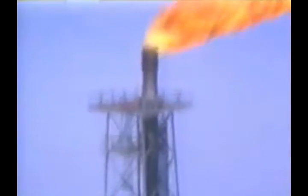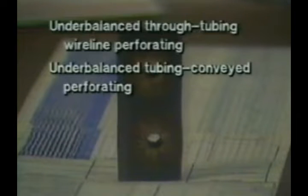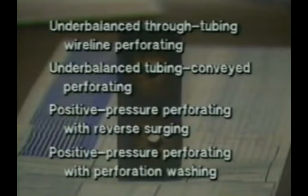Several researchers have suggested underbalance ranges for different permeability formations and different formation fluids, and these are given in Section 2 of your manual. In any case, a volume of fluid should be flowed from the well after perforating to remove perforating debris and improve the condition of the crushed zone. Wells should not be injected into before they have been given a chance to clean up. There are several techniques for achieving a high effective shot density: underbalanced through tubing wireline perforating, underbalanced tubing conveyed perforating, positive pressure perforating with reverse surging, and positive pressure perforating with